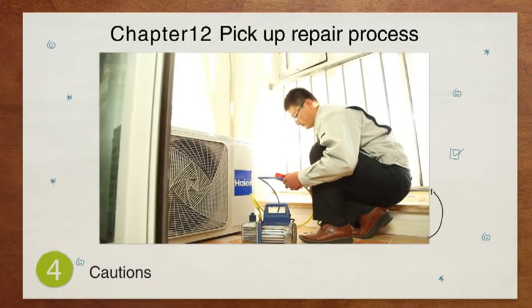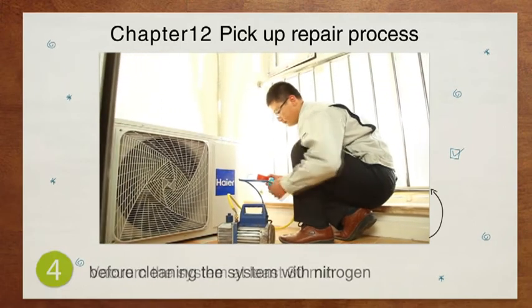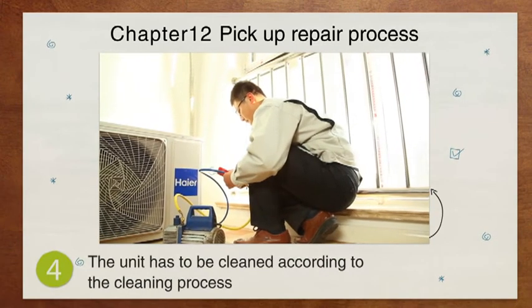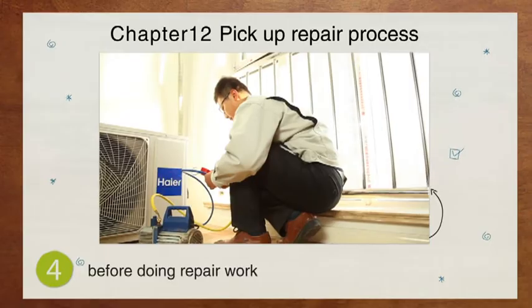Cautions. Vacuum the system at least 30 minutes before cleaning the system with nitrogen. The unit has to be cleaned according to the cleaning process before doing repair work.